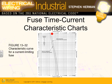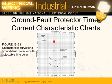If you have a fuse, the same thing. The fuse also has a time current characteristic curve that looks something like this, from the point it starts melting to the point it completely opens the circuit. The higher the current encountered by the circuit breaker, the faster the circuit breaker will open.